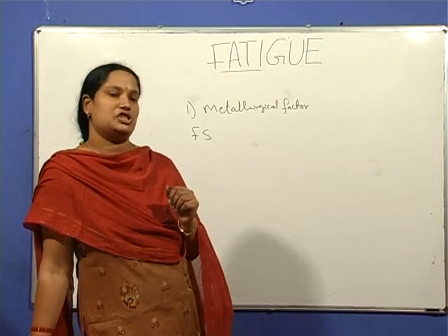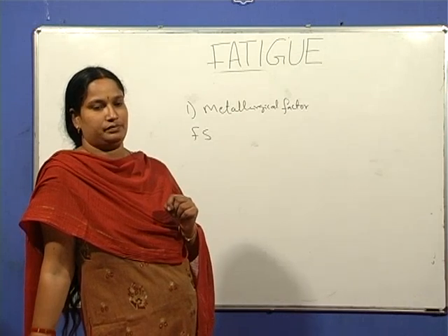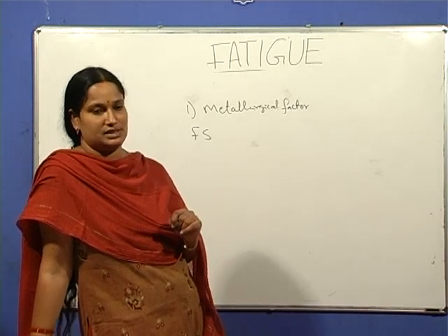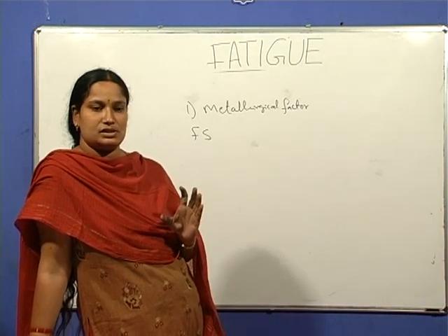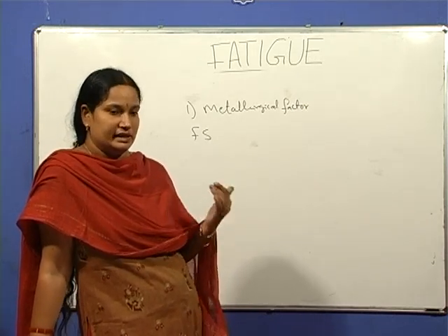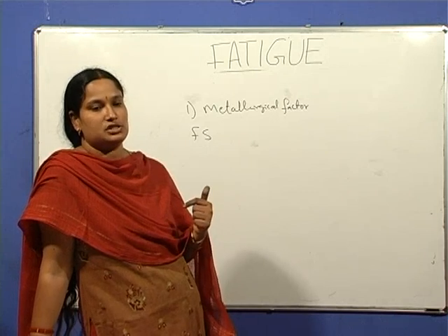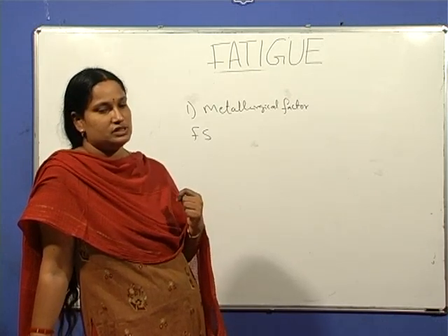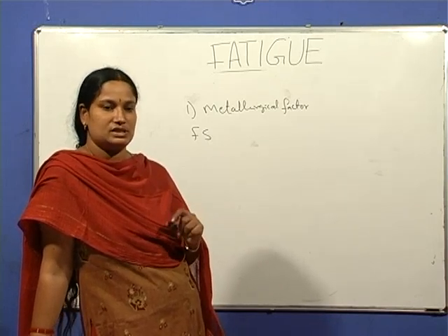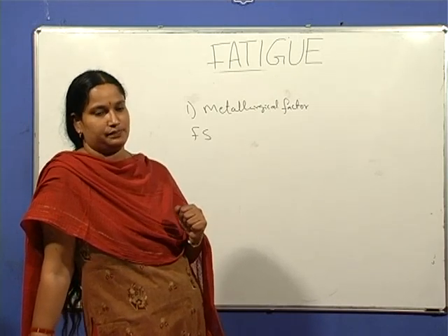there is some correlation between the fatigue strength and the ultimate tensile strength in the case of tension test. A higher strength material shows better fatigue resistance, but this is not generally so in all cases, because as the strength of the material increases, sensitivity to environment increases, as well as fracture toughness will decrease. For steels, up to around 40 HRC, Rockwell hardness number tested on the C scale, the fatigue strength increases with increase in ultimate tensile strength.